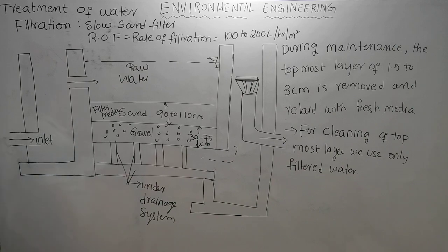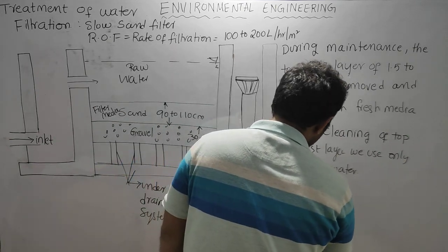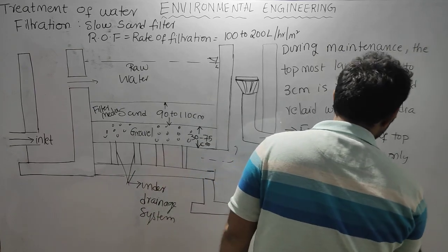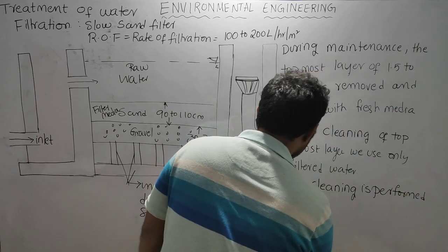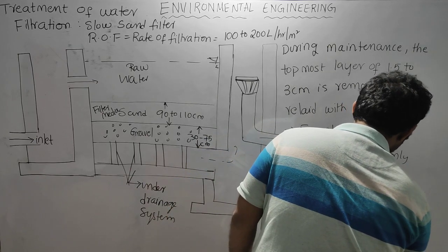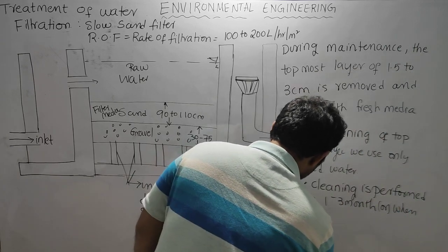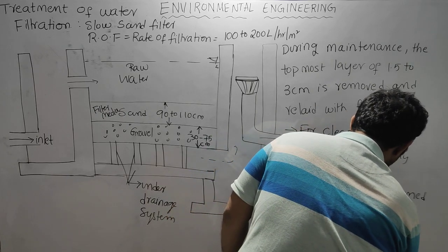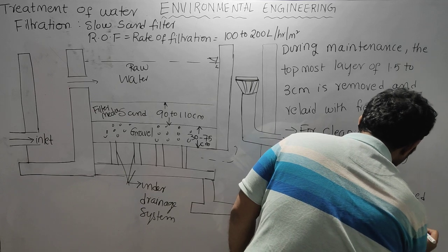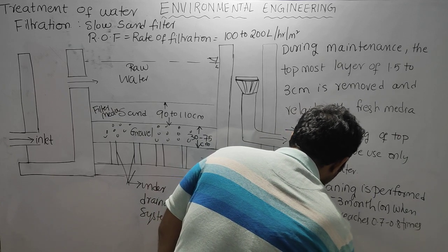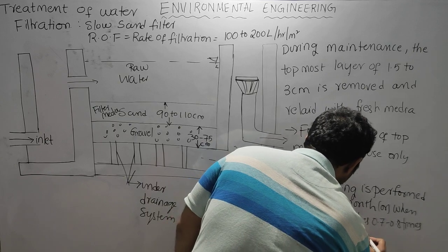Generally, this cleaning is performed once in 1 to 3 months, or when the head loss reaches 0.7 to 0.8 times the depth of the filter media, whichever is earlier.